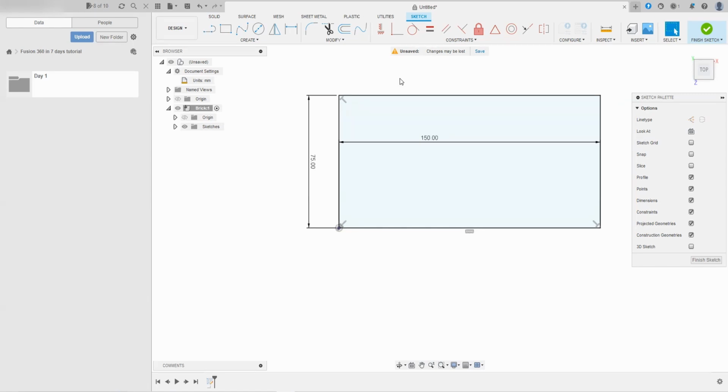The next thing that we're going to want to do is to ensure that our sketch is fully defined. This ensures that the geometry is completely restrained within the environment to prevent it from moving unintentionally when we use other commands. This is particularly important for parametric design, enhancing the accuracy and stability of the model and sketches. We will talk about parametric design in a later video.